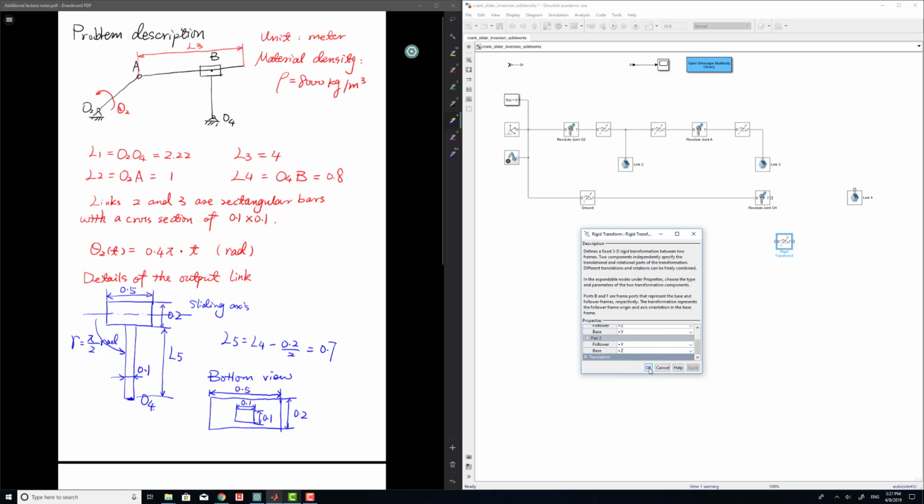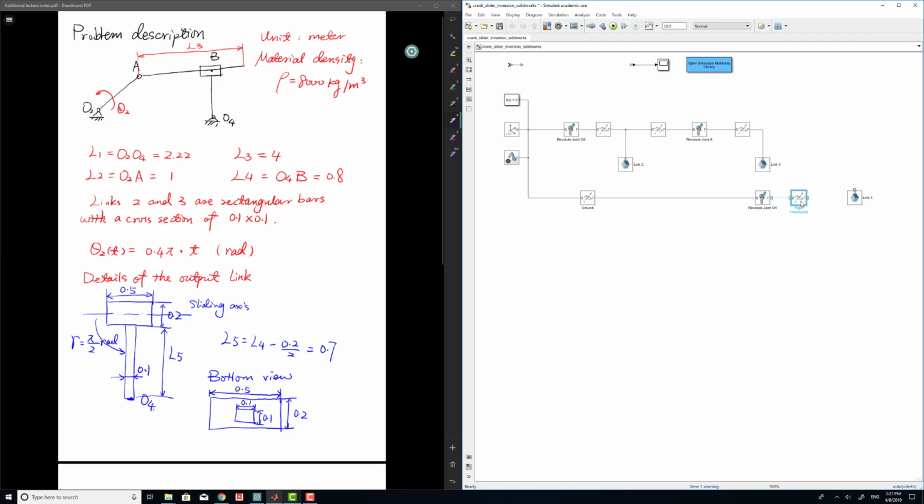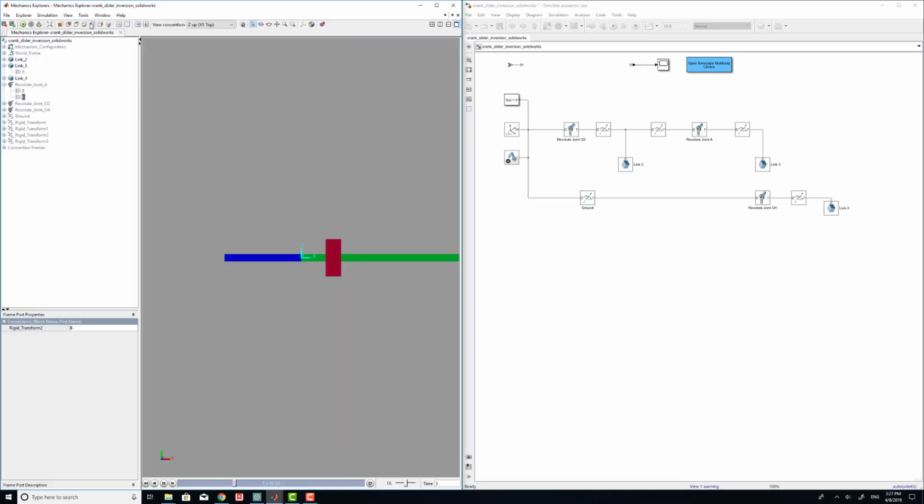In such a way, if you connect in here, after this transformation your rotation is no longer around z, but around y, because your y becomes z and z becomes y. And then you can directly connect your follower to the solid. Let's see what's happening. And you can click C. It's not that easy to tell, but these coordinates are correctly connected.